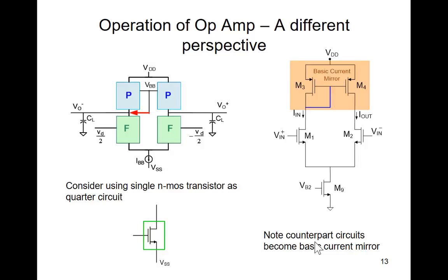Yes. Okay. I should have shown the load capacitance on there to indicate that we were steering that current to the load. Well, we're steering it 2 places. If you look at this output node, if you put in a small signal equivalent, there are 3 things hanging on this node. We're steering it to the capacitor and the 2 output conductances. Those 2 output conductances don't change. So remember, there's an output conductance, capital G2 here.